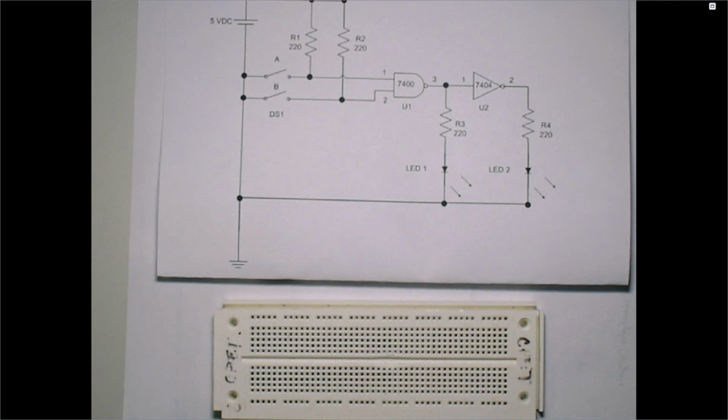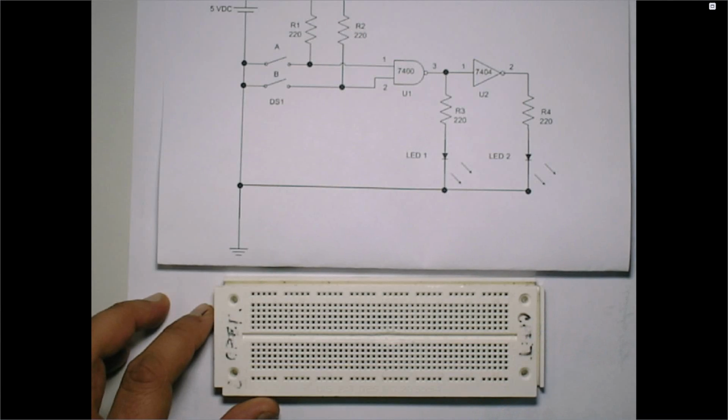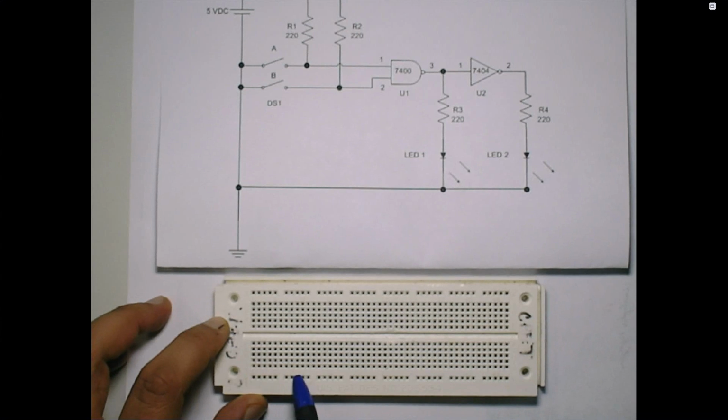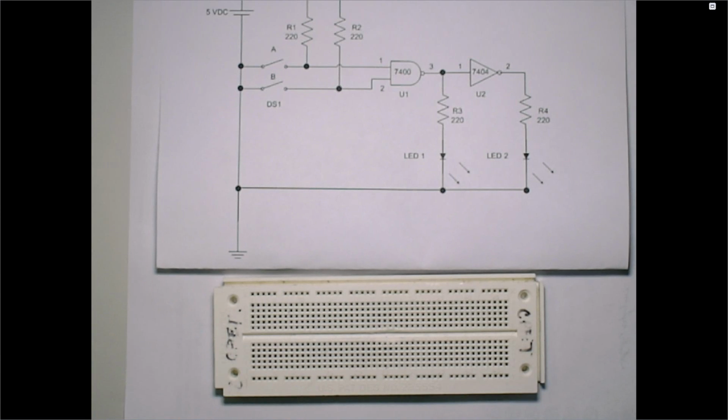Okay, so far we have some understanding of how the breadboard works, right? We know that this line is short, right? The bottom rail, this is short, right? This is also short along this line, but all these columns are short as well, right? And all these columns are also short, right? Each of the columns are short, meaning they're exactly the same point, even if you have like 4 or 5 points there. And you have a bottom rail and top rail, those are short as well, right? But you might have 2 rails at the bottom or at the top based on your breadboard. Okay, this is a very basic one. You might have a fancy one, right? Now let's start very quickly.